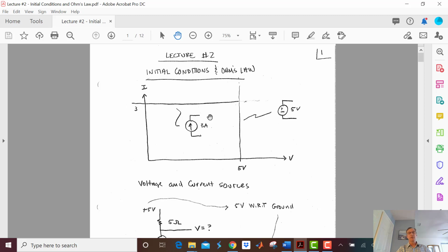So when it was connected to 4 ohms, we were okay because we had our 1 amp and the voltage was 4 volts. But we opened that switch and that voltage is going to go shooting up. It's going to actually be over in our neighbor's house or even further.